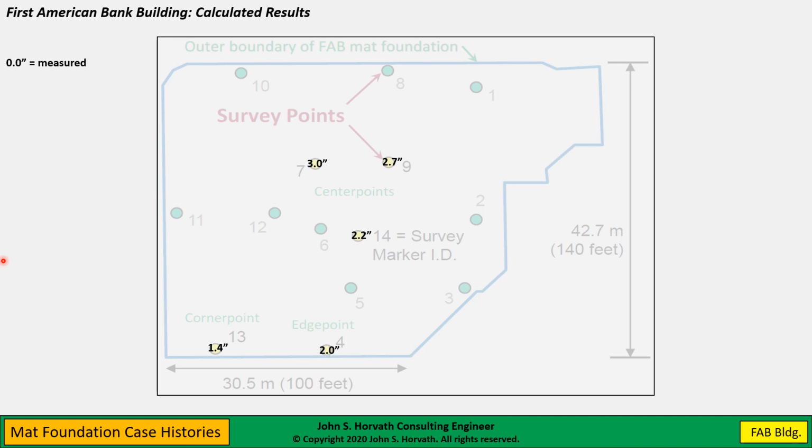First of all, I did an analysis assuming a single constant value Young's modulus, equivalent Young's modulus, single-valued shear modulus, and I calculated a maximum settlement of about 3.2 inches at the center and 2.3 inches at the edge. Now, in my analysis, I assumed an equivalent rectangle, 140 feet by 150 feet. So a pretty good match. Considering all the approximations, I think this matches the center and edge settlements pretty well.